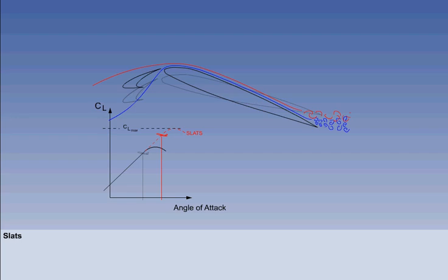There are two disadvantages with the higher nose attitude. Firstly, when rotating the aircraft for takeoff or flaring to land, there is an increased tendency to tail strike. Secondly, there is reduced visibility from the flight deck when approaching to land.